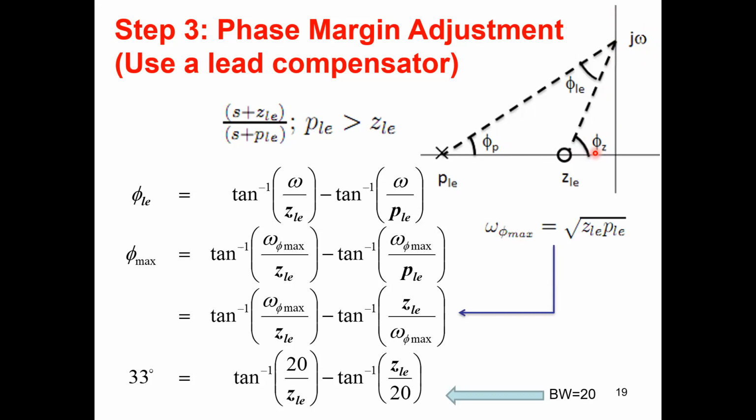Yes, both angles will reach 90 degrees and the difference will again be 0. So now you understand the lead compensator has no phase contribution added to the plant for low frequencies as well as high frequencies. So somewhere in between, you can have some significant phase contribution.